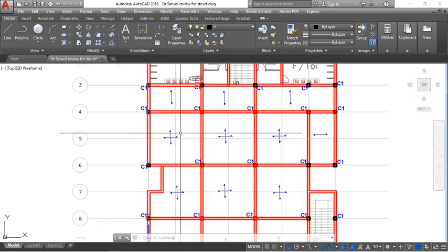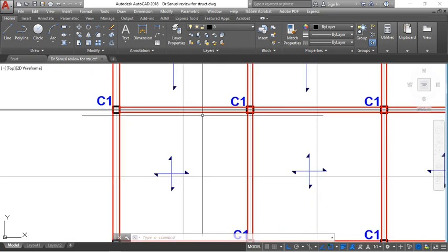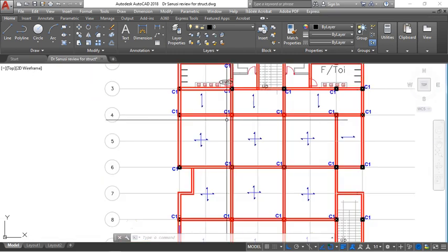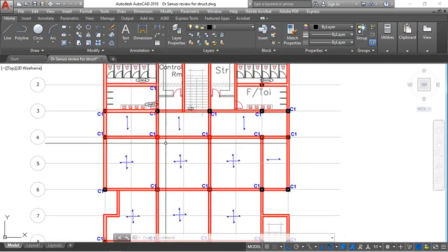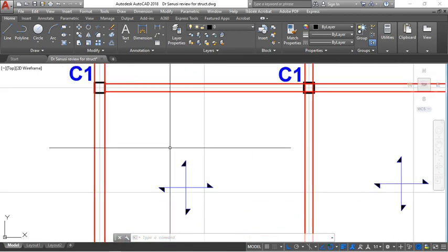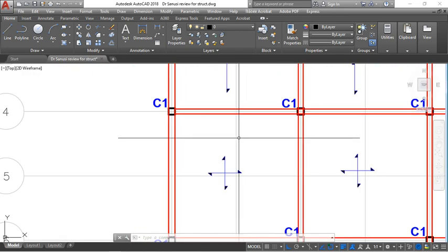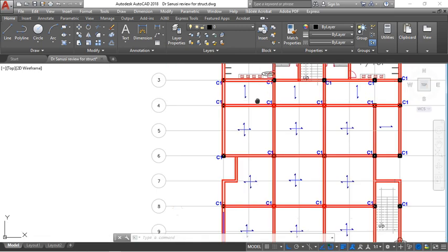So you have the beams and you have the slab, which will now have bottom reinforcement at the spans, then top reinforcement at the support. While the other way around, if it were to be raft, then you have the span reinforcement at the top, then you have the support reinforcement at the bottom.